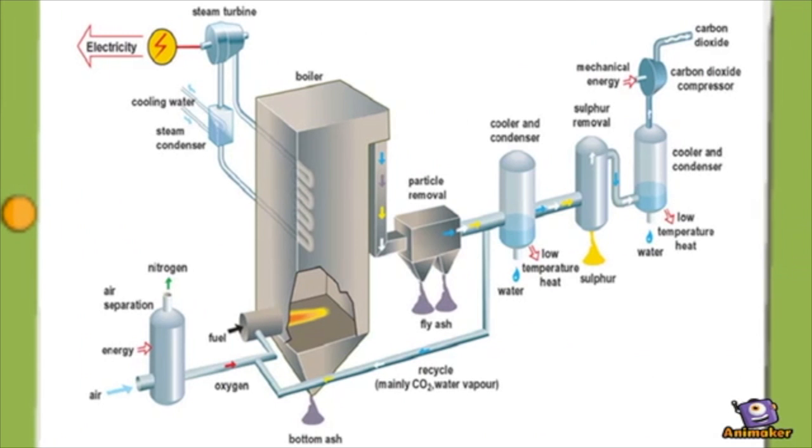An oxy fuel combustion system uses pure oxygen instead of atmospheric air in the combustion process. This removes the nitrogen and other gases from the reaction product. The outcoming flue gas is approximately 80% CO2 by volume. The remaining portion is mainly water vapor, which can be easily removed.